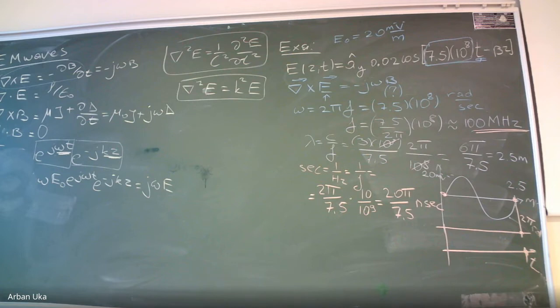How many data points do you need to draw a perfect cosine wave in 1 hertz? 20 data points is more than enough. 10 also would be okay, right? So if you have a signal of 1 hertz, you may need to sample a signal at 10 hertz, which means that you read 10 different values per second.